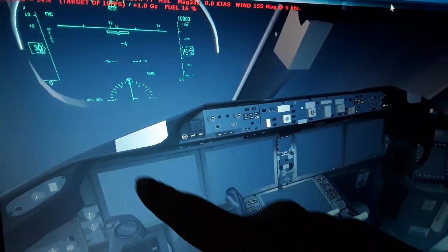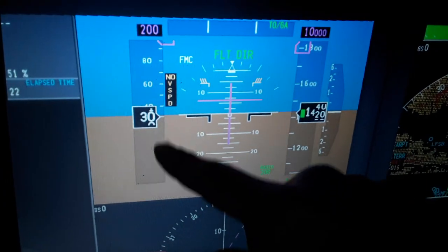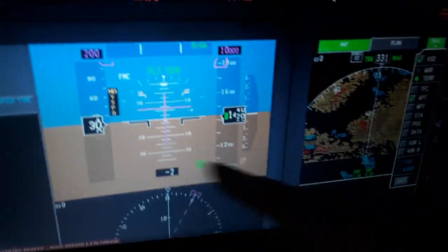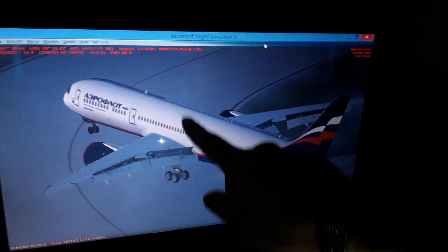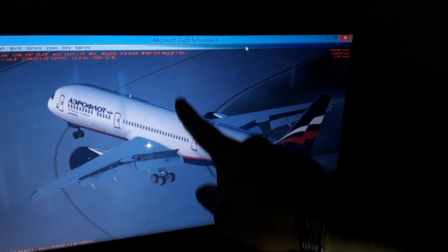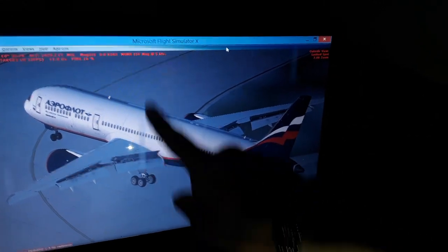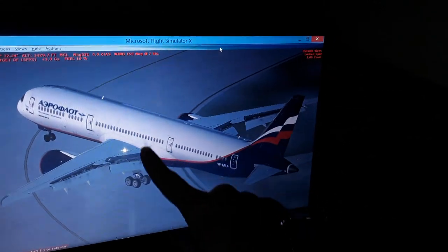You need to monitor here in the primary flight display the airspeed indicator. You will see red and yellow indication when flying at stall speed, you need to avoid that. Pull down the yoke or the side stick and increase the thrust to exit the stall condition. So you will see also that. So we have the aerodynamic chord with maximum aerodynamic lift occurs, is the position where the center of gravity is also positioned.